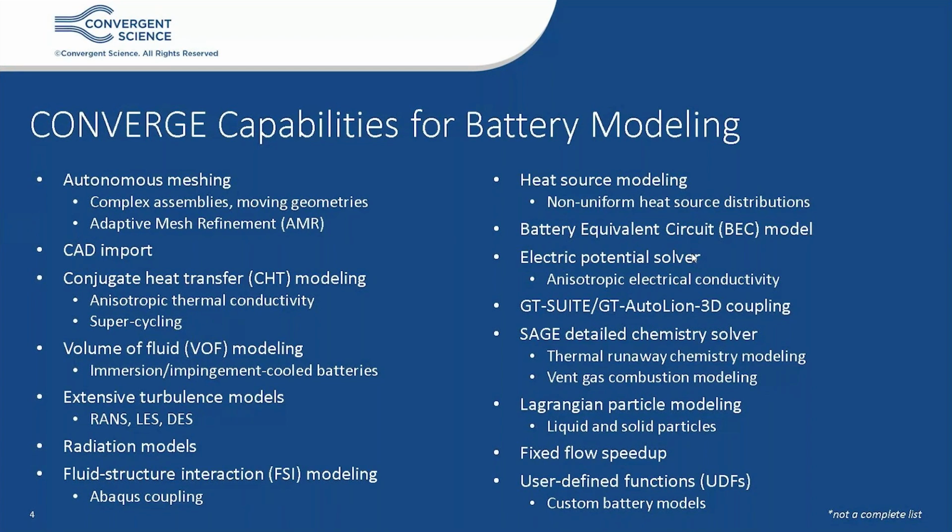To model the complex problem of battery thermal runaway, we make use of the SAGE detailed chemistry solver. We model the thermal runaway reaction rates occurring inside the solid, and also the vent gas combustion reaction rates occurring in the fluid domain. More physics can be included in your battery simulations.